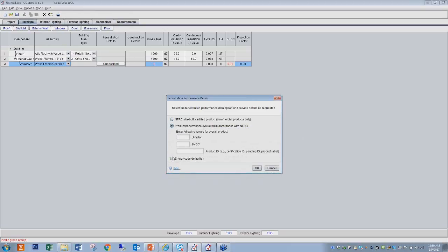Now, this is where typically most users spend most of their time. So, energy code default values in the commercial. Again, the worst case scenario, and for alterations, they are not going to meet it. You're not going to meet it because it's very prescriptive, right? Windows have to meet individually. Walls have to meet individually. For additions, you could do trade-offs, but it's going to be really hard to do. Their worst case scenario, but they're there.